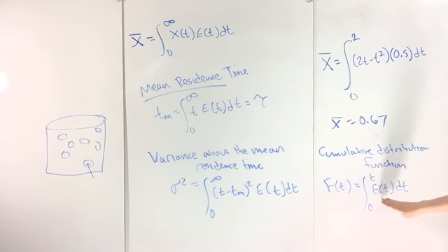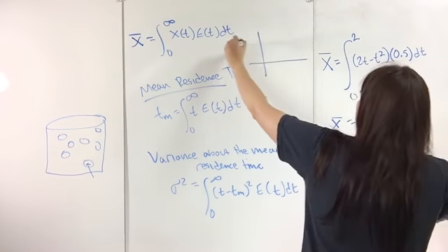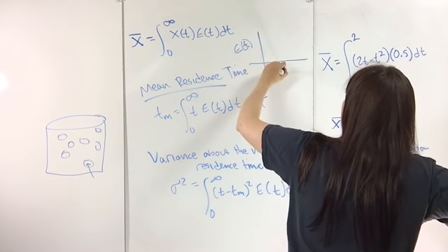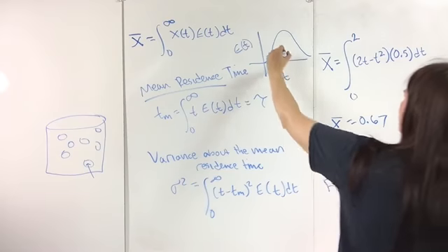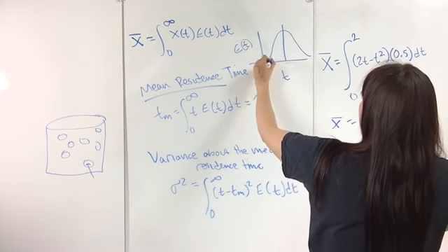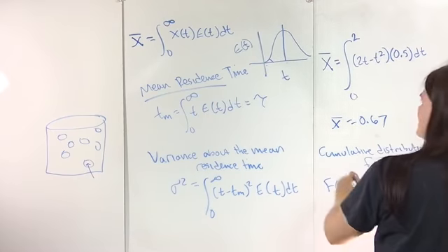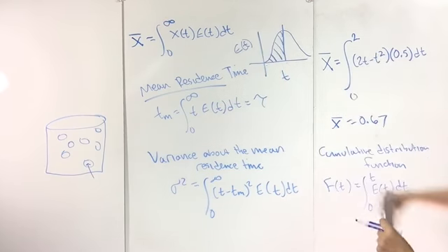And you can see how that would make sense. Because this residence time distribution function, so just draw that again. So E of t and t. So let's say it looks like that, and say you sum from here to here, then when you take this integral, you'll get this. So you're basically adding up what's been in the reactor.